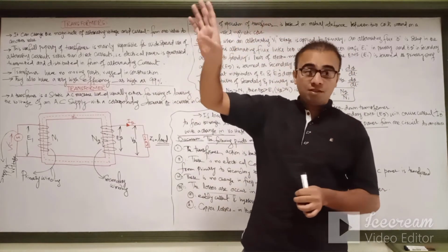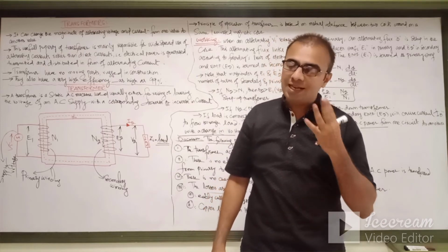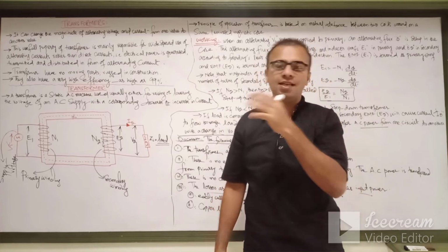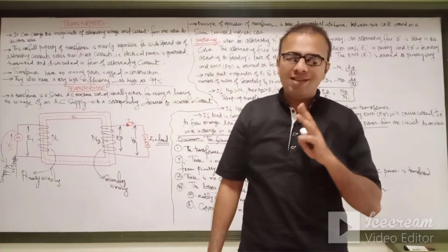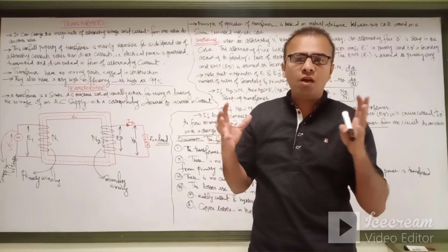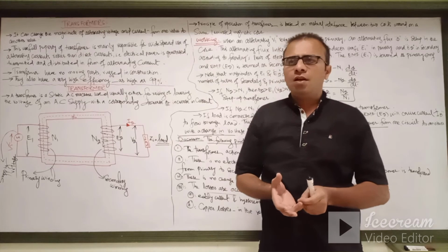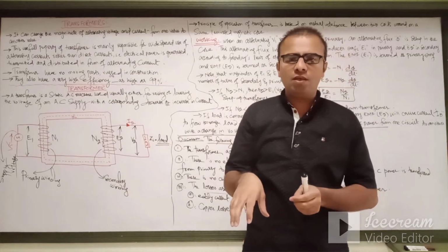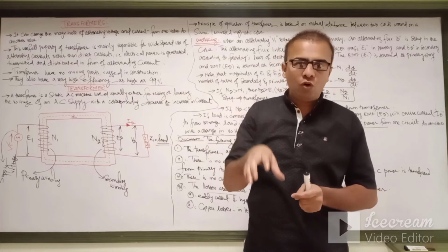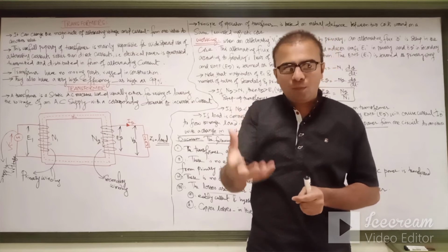Recalling the concept of hysteresis from basic electrical engineering, the hysteresis effect is the phenomenon of the flux density lagging behind the cycle of magnetization. But hysteresis loss totally depends upon which type of magnetic material we are using. Normally electrical machines are designed with low hysteresis loss, like silicon steel, which has low hysteresis loss, and this type of material is a ferromagnetic material.